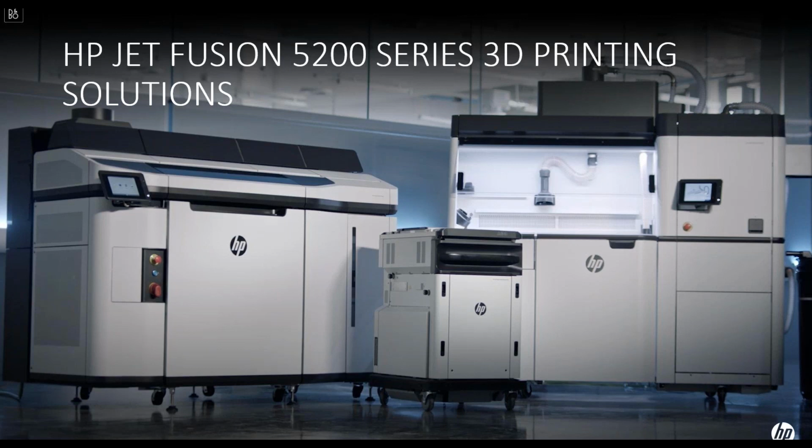When you set up a job, it is going to take the powder necessary to complete the job and put it into the build unit. The build unit then goes into the printer. While you're printing parts, you actually have a second or third build unit where you can start to post-process jobs that have completed, or you can prep for a future job. So these are really designed to run 24/7.